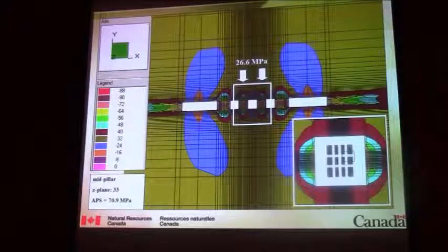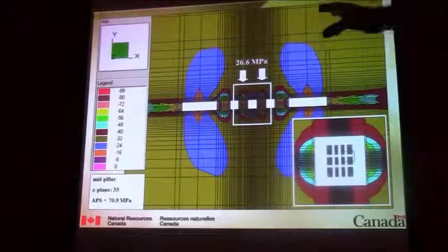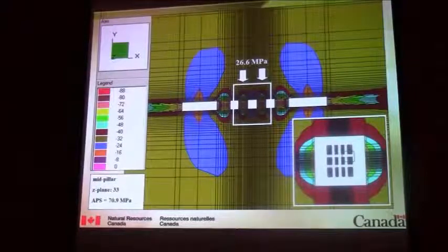I won't go into all the detail here, but the whole point was, as engineers working in rock engineering, we use numerical modeling tools which model the stress condition inside the earth, and we use that to choose between different mine designs. For example, how big should your pillars be, how big should the gaps in between, the stopes, the areas that you mine out. We use numerical modeling tools to make decisions around this, but we need good input data: rock strengths, rock properties, rock behavior.